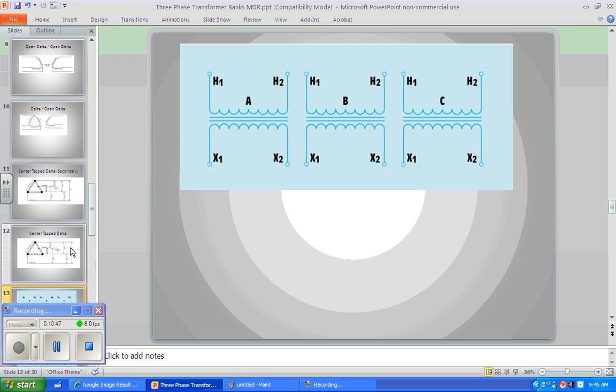So then we're going to look at the line coming into the load, and then we need to look at what happens in each phase, because when we're doing calculations, we need to stay in phase. We want to stay in phase to do our calculation. And once we have our calculation for our phase, then we can go back to our line and our load, and from that we can go back to our line and our output of our transformer. Then we can look at the phase of the output of the transformer. And we're looking at the currents as we go back up. So we get the voltages going down to find out what voltages are across the phase of the load.